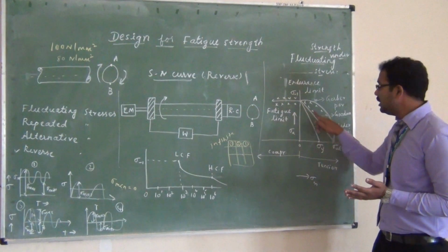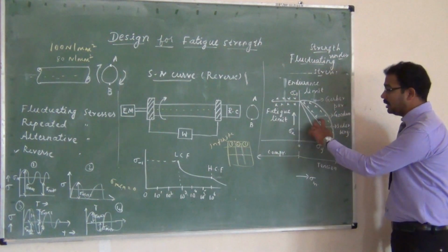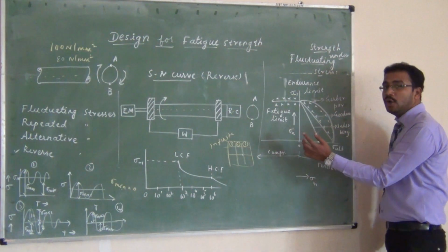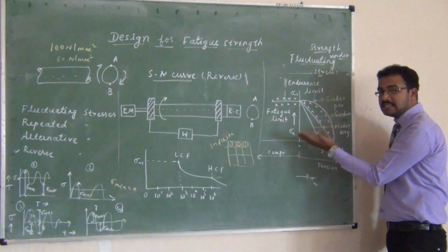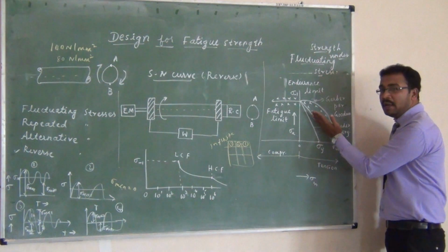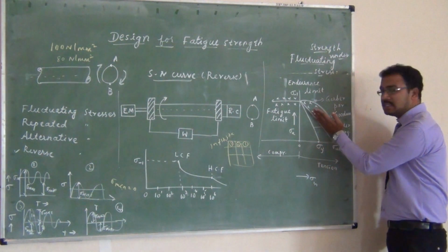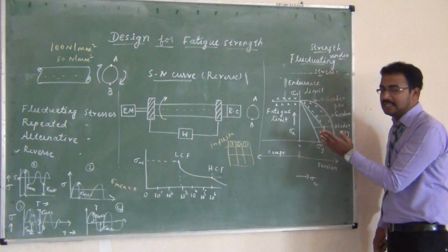This scatter point shows the different material properties. So when I am talking about this Goodman's line, without any confusion, I can directly go with any particular point. Again, the same case is applicable here: in case any material's characteristics cross this particular line, we cannot recommend that particular material for any design purpose.